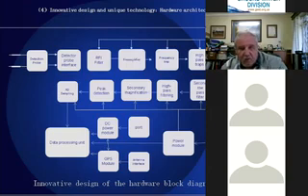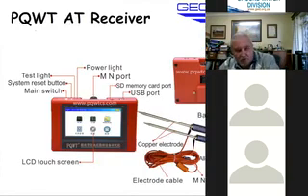A lot of people have seen the equipment and actually use it. What you have over there is your console, a touch screen pad, much like a cell phone, also not very visible in the daylight. You have your copper electrodes, well, they call them copper, they're actually brass electrodes, and the aluminium on top, and you have the cable. Your separation is always 10 meters, because it's calibrated for a 10-meter separation.